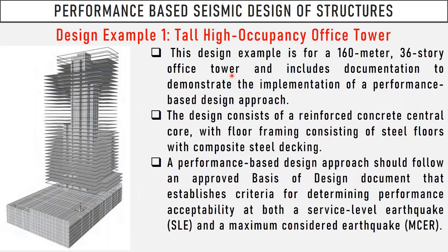Again, just to give you an idea, this is an example from the PEER website. As you see, both the core system, which is the lateral load system, the preliminary gravity system, and the foundation are all in the mathematical model, since the foundation input motion affects the structural response. Of course, you will do the service level earthquake analysis, then the maximum critical earthquake analysis, and check.